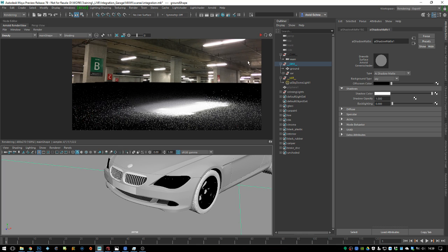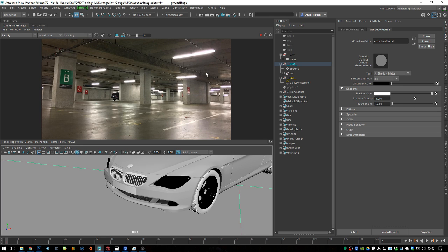Well, in the render, I try to match the blacks as closely as possible. But there you will always get a mismatch, because in the plates it is mostly lifted a bit. So it's hard to do this kind of effect in lighting. If you want to do that, you would need to fake it by creating an ambient light or something similar to get the same effect. I will show you in a second what I would use for that. So progressive is off, and let's just render this. So now I'm just rendering out the shadow mask.